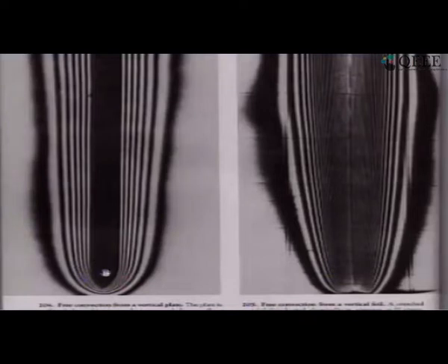And what you see here is that the plate is all black. Far away, the fluid is all white. So here it is at constant temperature, and then we begin to see one band of dark followed by another band of bright, then a dark line, then a white one, then dark, white, like that all the way to the plate. And if you go very close to the plate, you will see that next to the plate there is a continuous bright line. So what each line represents is one particular unique temperature.